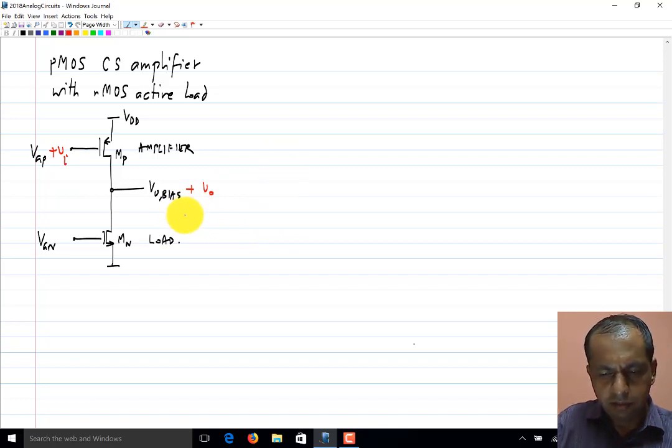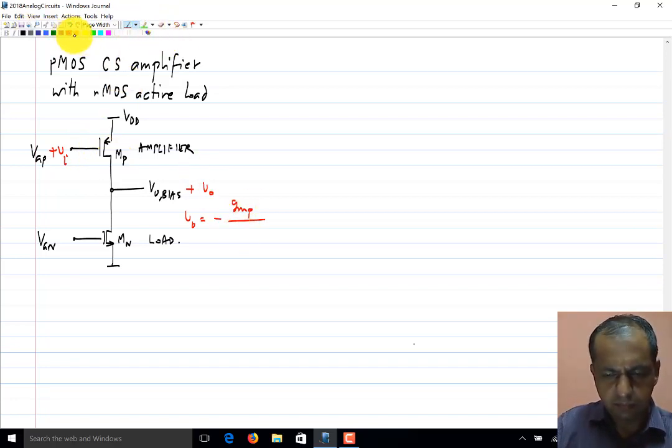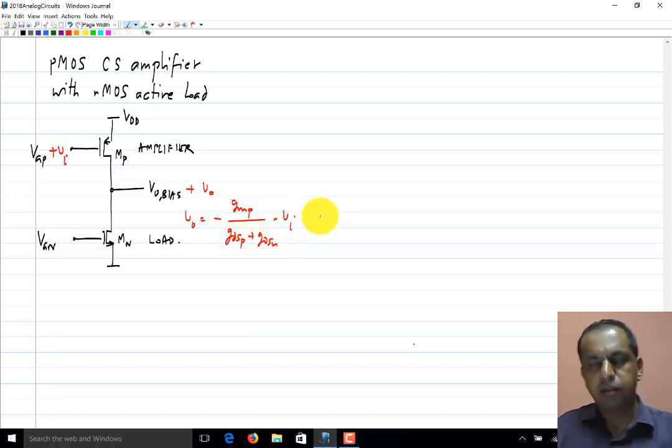We know that VO would be minus GMP, which is the GM of the PMOS transistor, divided by GDSP plus GDSN times Vi. Okay.